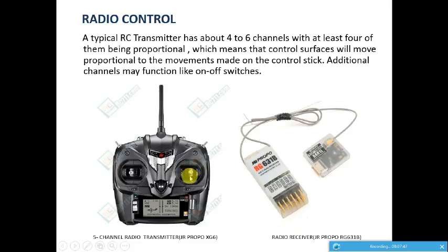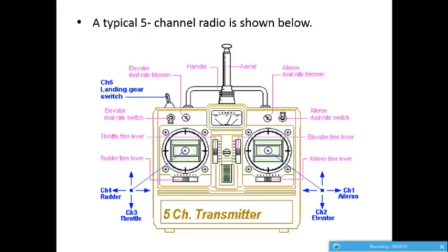So these are the control sticks and the control horns, switches, which enable it to function as a 6-channel radio. These two control channels which are here give 4-channel controllability, and these two additional switches or control sticks extend the channel count by 2, giving 6-channel controllability.